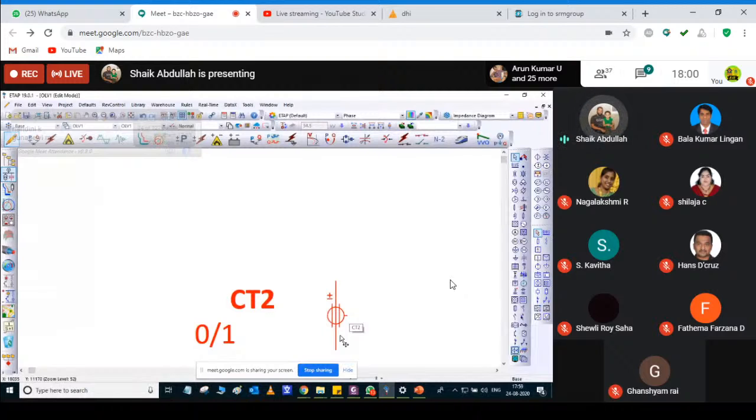Usually in a CT, what is the basic principle? One CT for one phase, and only one conductor is allowed through your CT, the conductor whose current you are going to measure. That is the usual procedure. But when it comes to the CBCT, it is quite different. All outgoing phases of that particular equipment, which you are going to protect, pass through it.